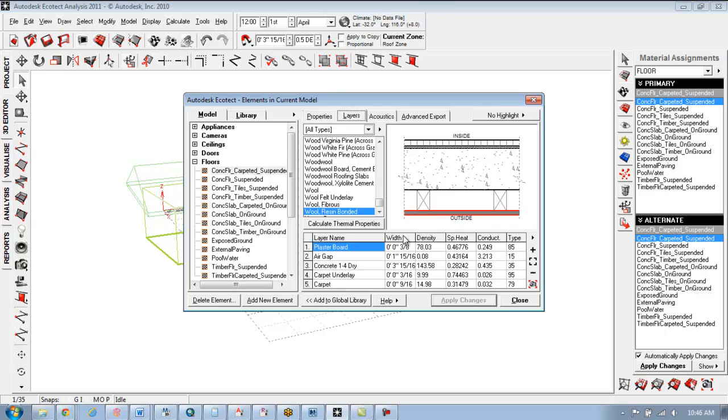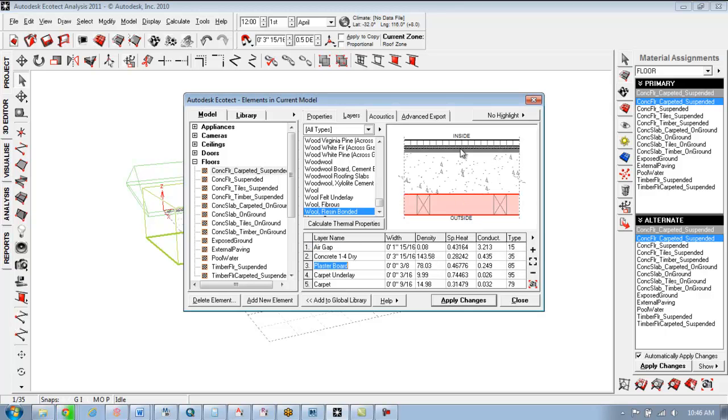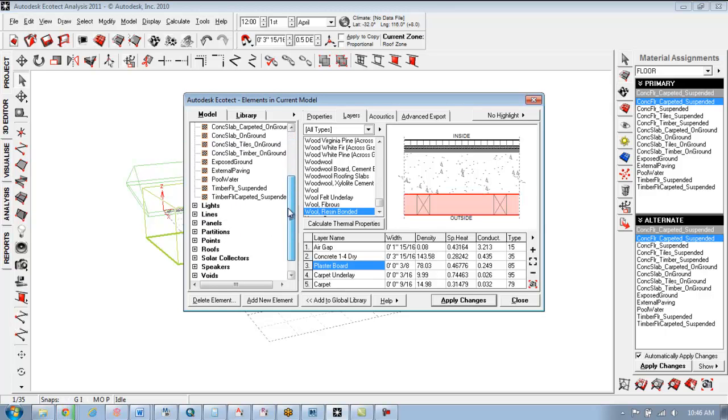Any questions on that? It's kind of straightforward. It's sort of drag and drop, and then you can move things around and it'll adjust and tweak it, and then you can set the thicknesses and it'll actually adjust in this little display screen here. So it's kind of nice to be able to use. And then it shows all the different options on the side here of what you can select, what you can do with it. And then you can actually create new and add to your global library. So if you have a standard wall that you use in Revit, you can add it to your Ecotect library and then just easily assign it to the zones.